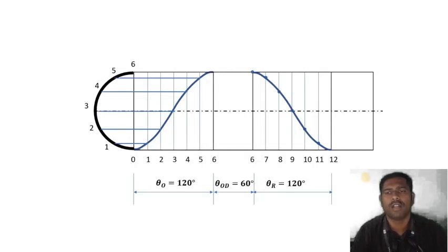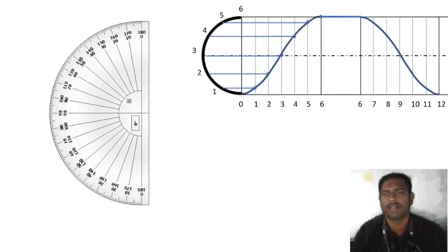So the follower is moving from the maximum point to the rest condition, or the return condition, with 120-degree rotation with this point of contact with the cam, and the remaining 3 centimeter will be taken as return dwell that need not be marked here itself. So the maximum line for us here is 15.